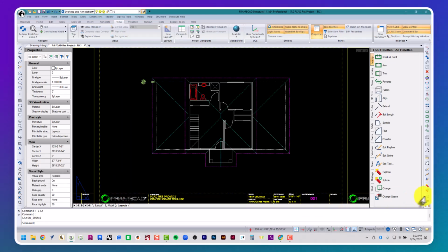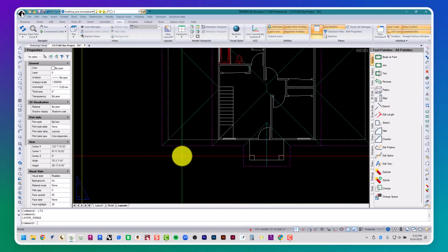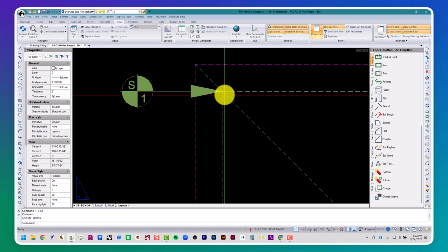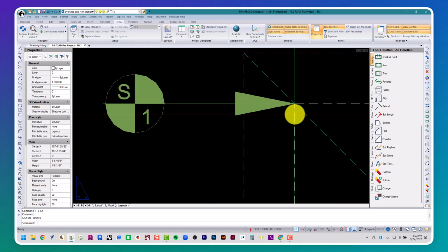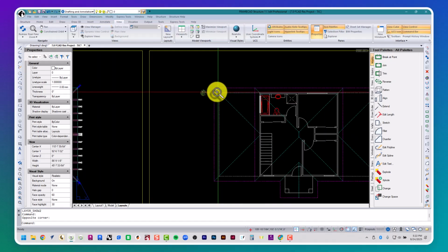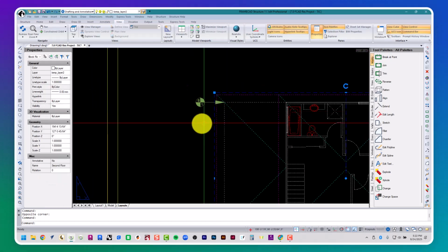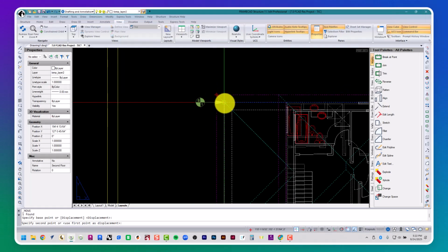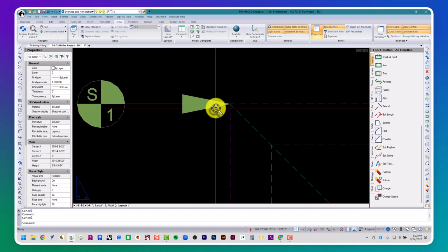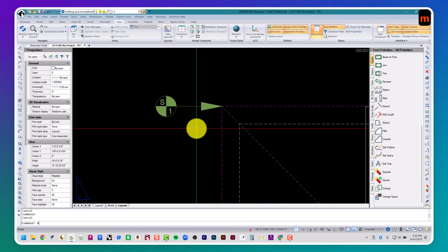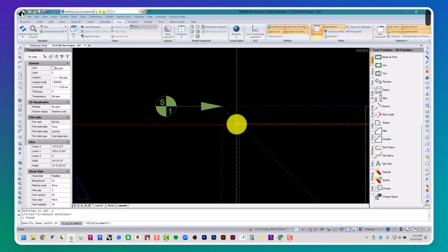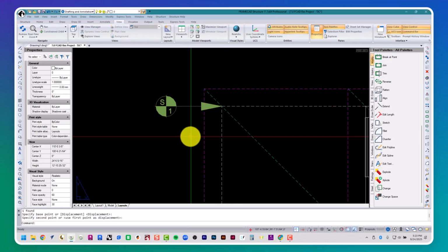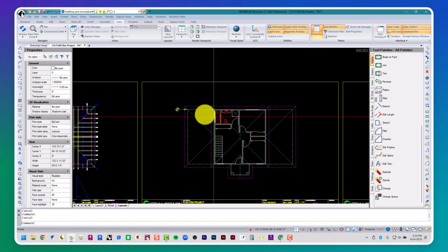This is only going to work correctly if you imported the second floor plan and set it to temporary layer 2. Zoom into the reference point and make sure that your block is lined up with this reference point, based off of this corner here where the walls of the first floor meet this reference point. If yours looks more like this, where the roof lines meet up with the reference point, just simply use the move command, select this object, move it from this corner to the reference point itself, and that's how you fix that. Don't move the reference point.